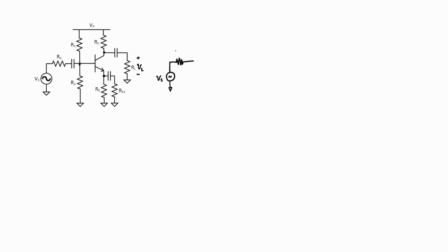Well, we've just reached a capacitor, and I'm now going to assume, again, that the amplifier is well designed. That capacitor actually forms a high-pass filter with the input impedance of the amplifier, but we're going to neglect it. In other words, we're just going to assume that the capacitor is large enough that the AC signal can just go right through it like a short circuit. We now have two branches. We have resistor R1 that leads to a DC source, or an AC ground equivalently, and then we have resistor R sub 2 that leads down to a real ground.